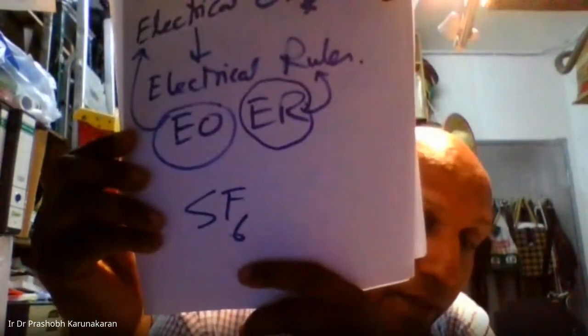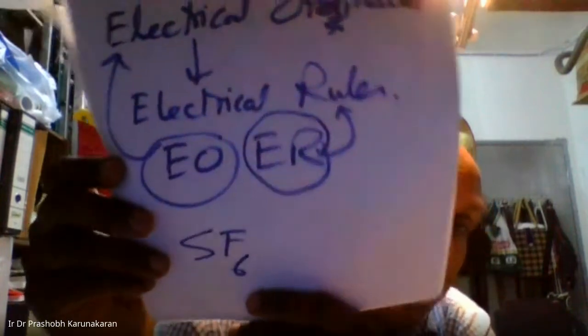So an electrical system like an MCB is designed to take away the arc. How do they do that? They blow at it. The arc will become thin and long. The thinner and longer the arc gets, the safer it is. So that's how you handle arc. How do they blow? Most of the time in the history of mankind, they used oil. Now they're using a gas called SF6, sulfur hexafluoride gas. They're blowing at the arc.